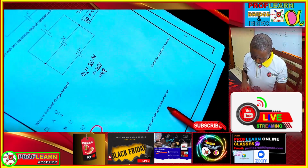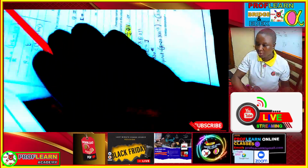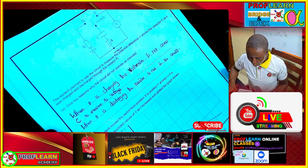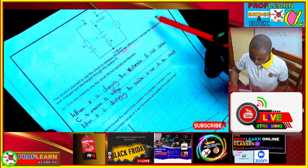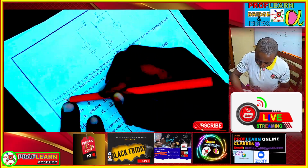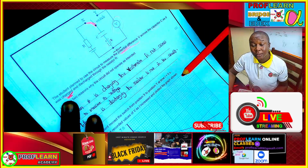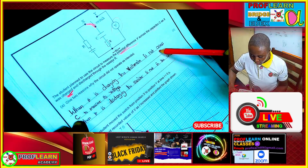The student investigating a capacitor set up the circuit as shown below. Those guys who asked me to do Excel, capacitance, charge, I believe now you are enjoying this. Give a reason why the circuit did not operate as intended. The student planned to use the circuit to measure potential difference across the capacitor, but as it was charging, this should be connected here, right? So as it's being charged, this is disconnected. Which means when it's charging, the voltage is not across C, so it will not be able to measure. That's why it failed.